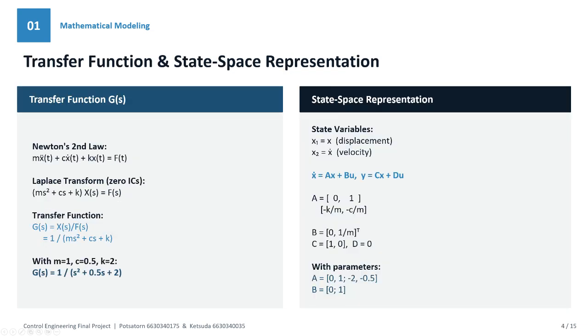However, analyzing differential equations in the time domain can be complex for control design. To simplify this, we applied the Laplace transform to transition our model into the frequency domain. This allowed us to derive the transfer function, G(s) equals 1 over ms squared plus cs plus k.